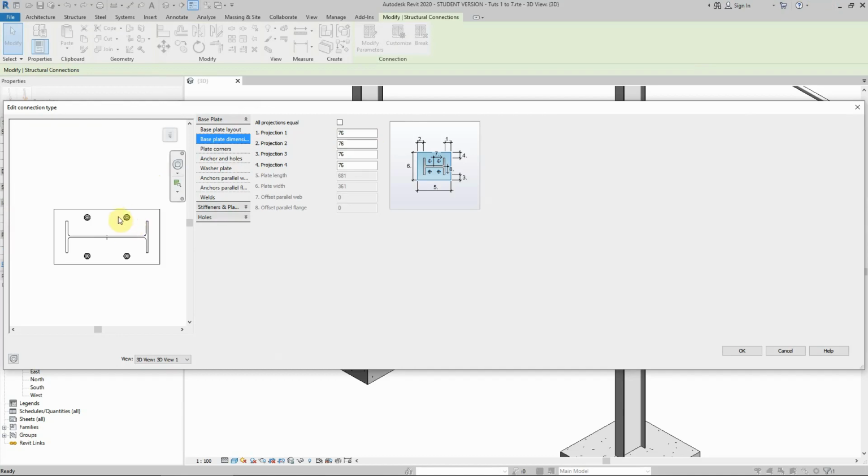But if I look at the bolts here, just so you know, my plan is we need to have one bolt on the outside, another bolt here, the same thing on these sides. So we'll have 2 bolts here on the outer side, 2 bolts inside the flange, and another 4 bolts on the other side, mirrored to that side there.